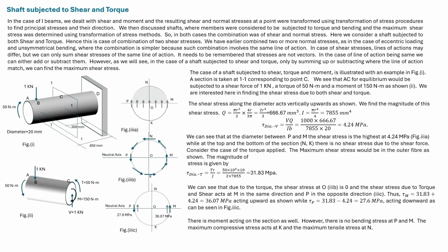Here we will deal with a shaft subjected to shear and torque. When dealing with eccentric loading, we summed up normal stresses due to moment and axial force to find the stress at an element. In the case of a shaft subjected to shear and torque, we'll sum up shear stresses.